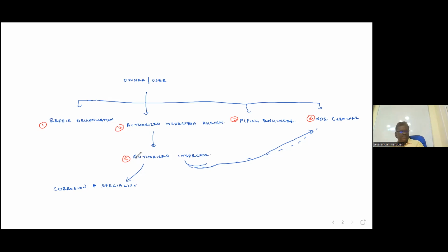Right. Now, actually how it works. So we have different types of inspection. I told you internal inspection is not normally conducted on piping. Next one, external inspection. External inspection means we will check the outside condition of the piping completely. Third one is called on-stream inspection. What is on-stream? Checking the inside condition from outside by using RT or UT. Now the problem is on-stream we cannot check complete piping. It is practically not possible. Completely doing UT or RT is not practically possible.